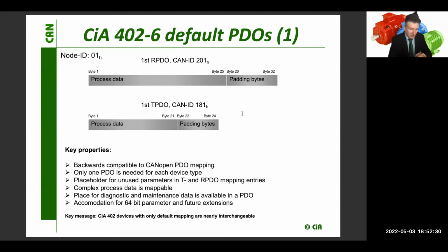So for example, if I have position control, then in transmit PDO I need to send the status of my drive, then the actual value I am currently monitoring, and some further information.